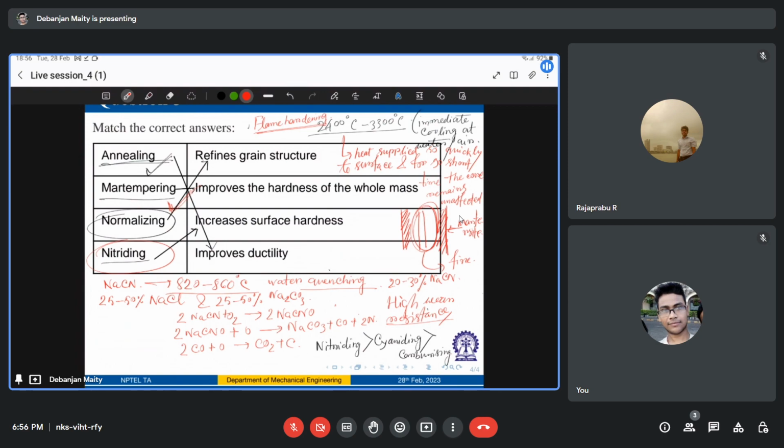And in terms of disadvantages, the thin section may get distorted extensively, and overheating may cause cracks. So these are some advantages and disadvantages you can think of. Now, in terms of induction heating, what happens during induction heating? There is something called flame hardening, where you are heating through the oxyacetylene flame. The heat source has basically changed in these hardening methods.